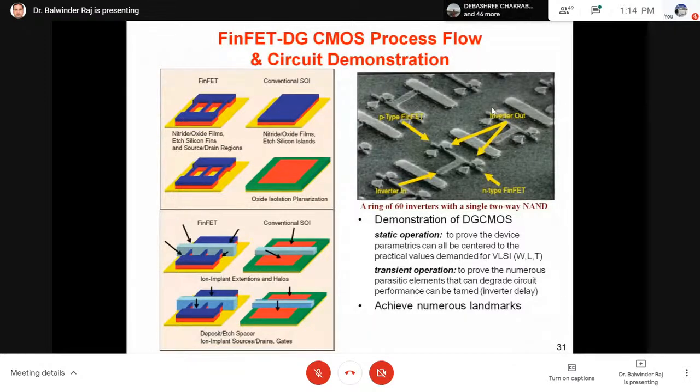We can go for the 2-input NAND gate, and once NAND or NOR is designed, any type of logic we can design with these universal gates designed with the FinFET. So first the FinFET is used for the inverter design, NAND, NOR, and based on that all types of logic can be designed, which is the standard used for VLSI circuit design.